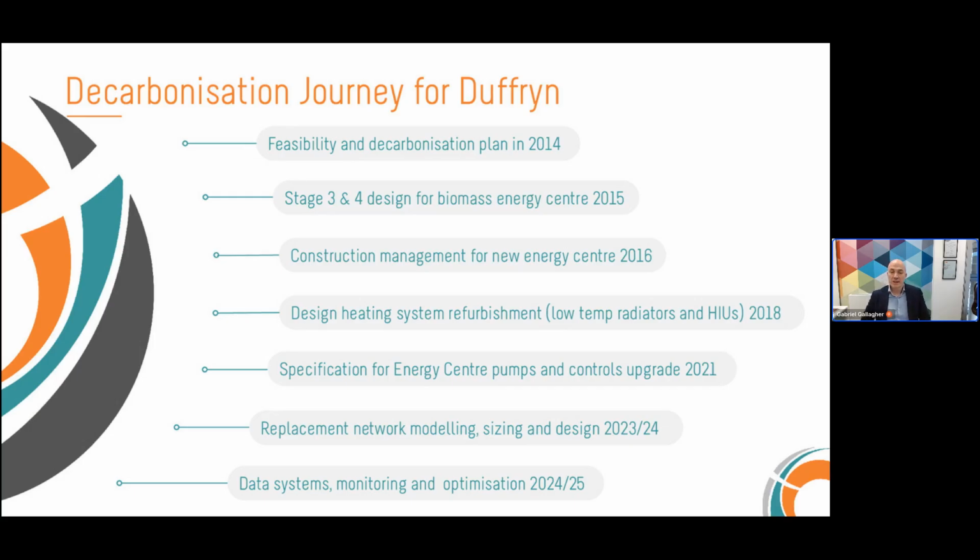Once that was complete, we did a specification for the existing, old gas-fired energy centre to upgrade pumps and controls to manage flows and temperatures, and then in 2023 an exercise around options for replacing the existing network as it came to its end of life, which led on to the installation of a new network, and ongoing data systems monitoring and optimizing that network.